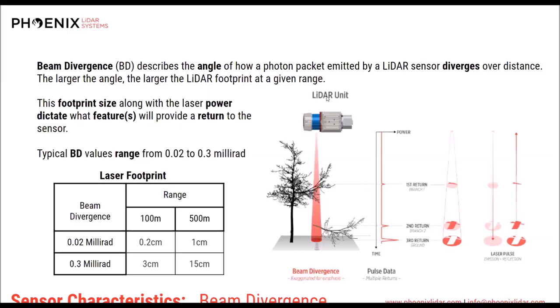Okay, let's change directions a little bit. And here's another question that we hear a little bit about often as well. How many GCPs are needed, and what would be the geolocation accuracy for different families of sensors? I recommend a similar ground control array for whichever scanner you're using. My idea of ground control array is much more project specific, acreage specific.